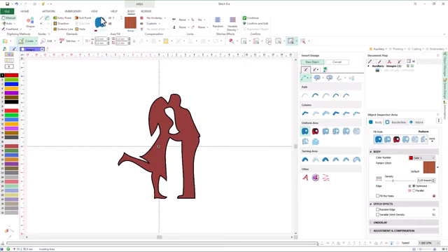When we start any of the object creation tools, the first geometric element to digitize will be the main contour. Once the main contour is defined, we can digitize the holes, add direction lines, etc. As we have already started the tool, the system is waiting for us to digitize the main contour. The default digitizing mode is manual, so we will change it to auto trace.